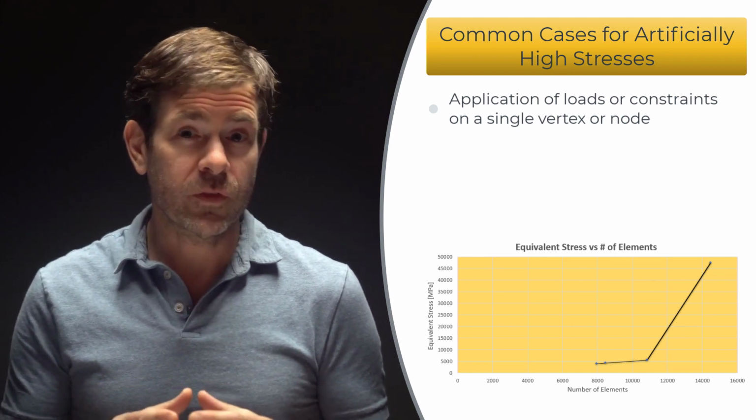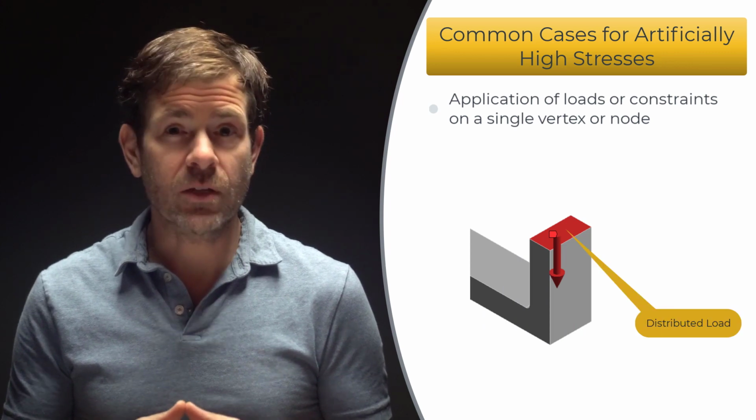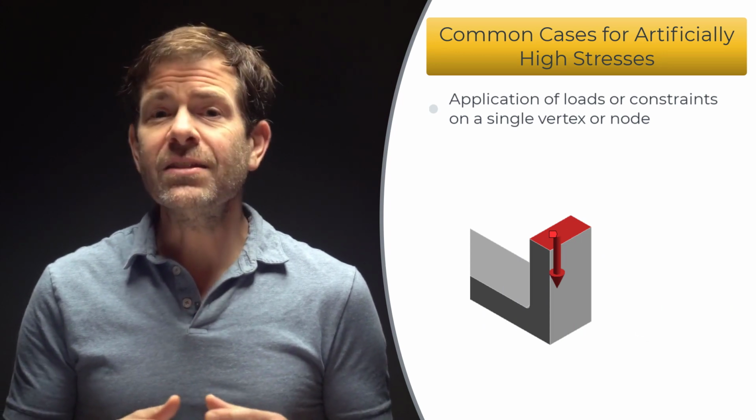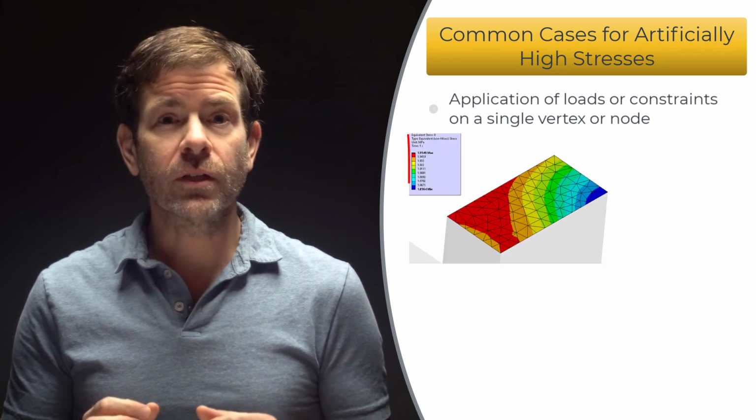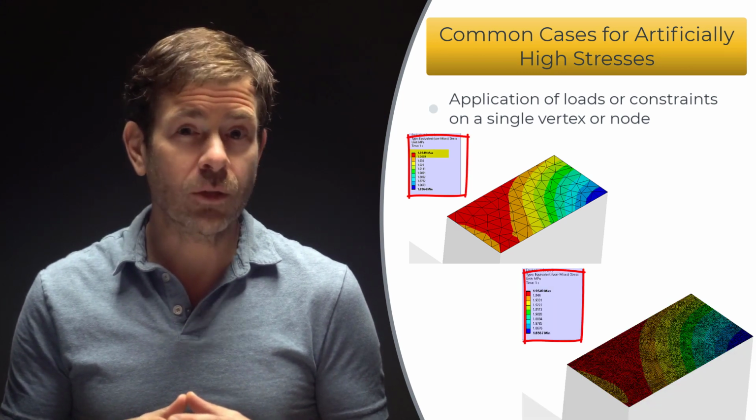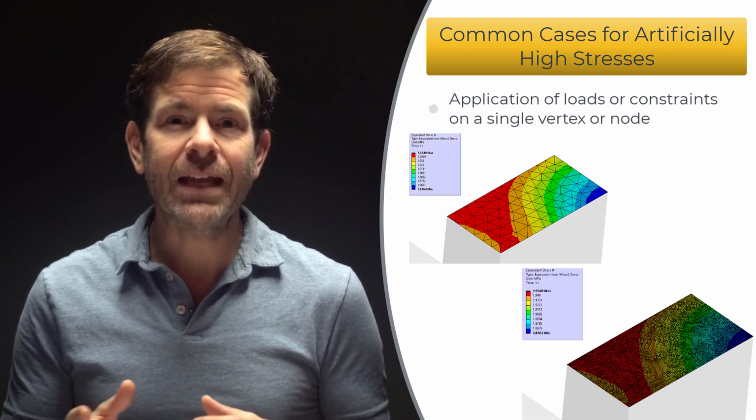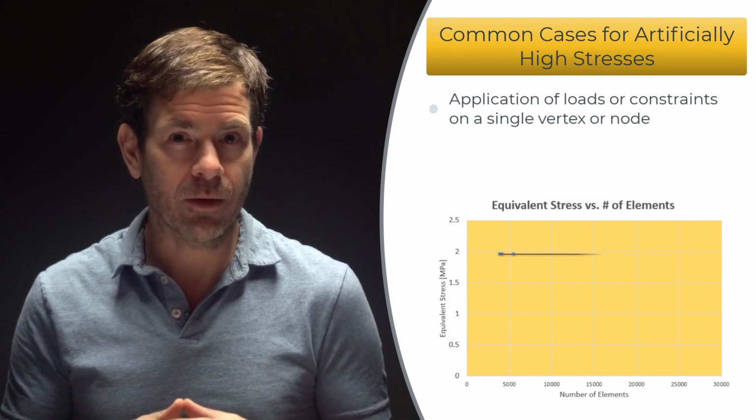For solid and surface geometries, apply the constraints over lines or areas. In these cases, as the mesh is refined, the total area the load is applied over does not reduce, and hence the stress does not increase without bounds.